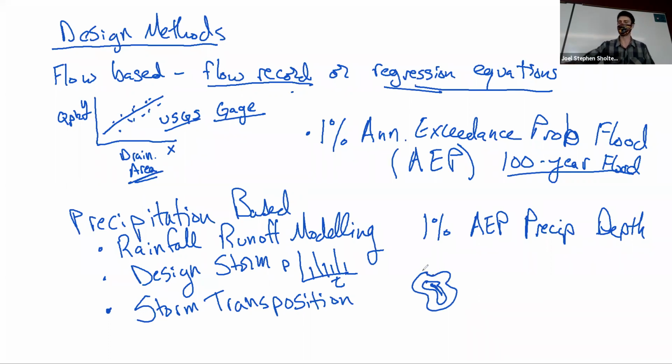Well, we can take a storm event. Say we have this radar record of a crazy storm event, like the September 2013 flood on the Front Range. We can say, okay, over 7 days, this is what the rainfall looked like, if these are rainfall contours here. So maybe we had 4 inches fall in the middle, 2 inches, 1 inch, 0.5, something like that.